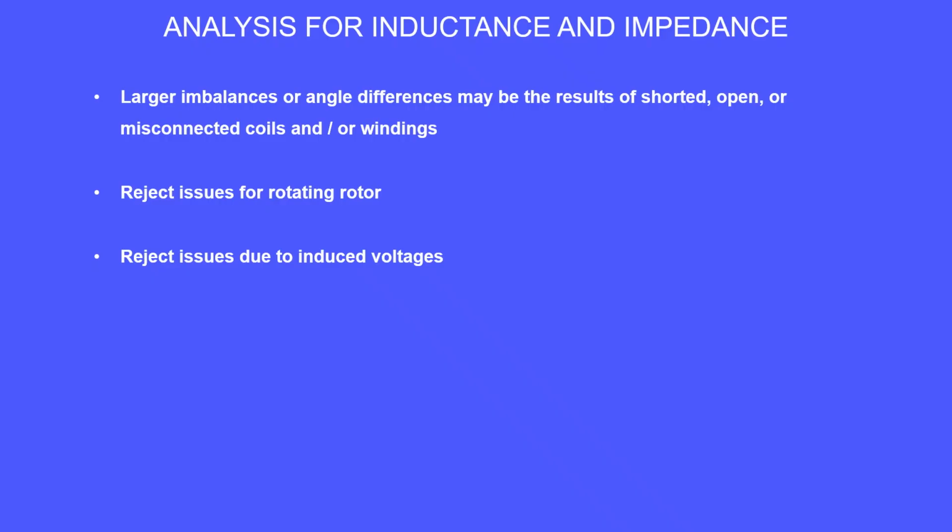Larger imbalances or phase angle difference may be the result of shorted, open, or misconnected coils or windings. We must be sure to reject results due to the rotor rotating while testing, or issues from induced voltages.